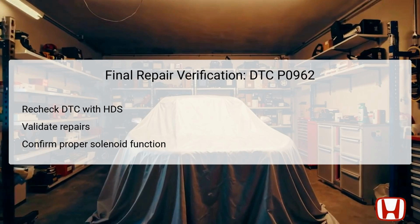After completing the repairs for DTC P0962, it's essential to conduct a final verification to ensure that everything is functioning correctly. Begin by rechecking for any DTCs using the HDS. Make sure that DTC P0962 is no longer present, confirming that the related issues have been resolved.